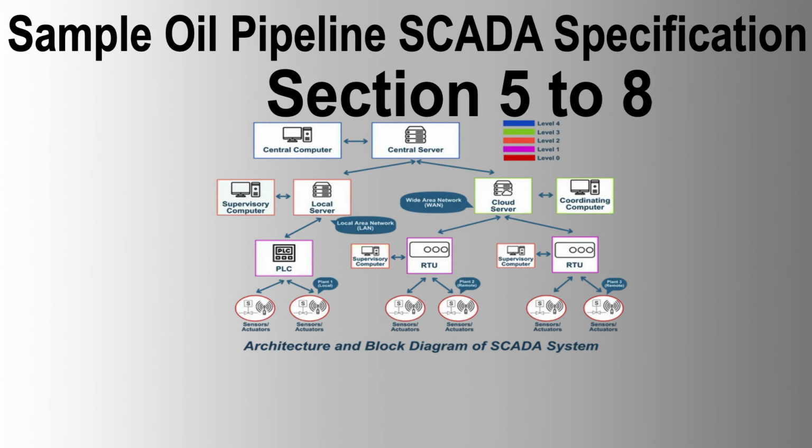6.7.1 General. Installation and wiring of all panel-mounted equipment shall be in accordance with applicable Indian standards, codes, and local statutory regulations. 6.7.2 System Cables. Intercabinet cables shall be of prefab type with plug-pin connectors at both ends for faster commissioning and lower wiring errors. Seller shall provide a schematic diagram showing cable types, plugs, terminals, and involved panels.